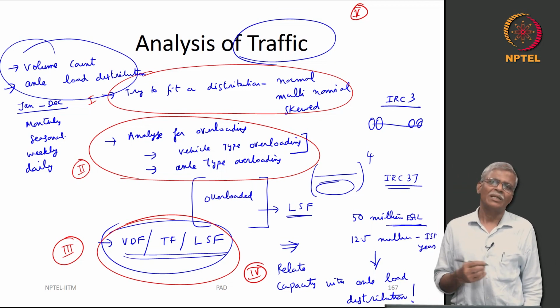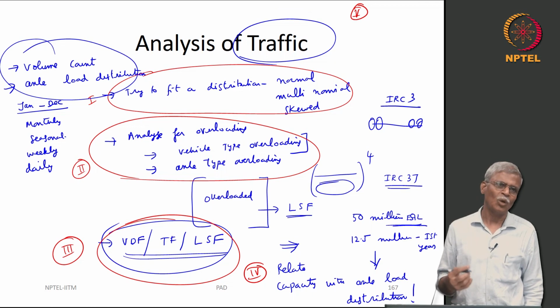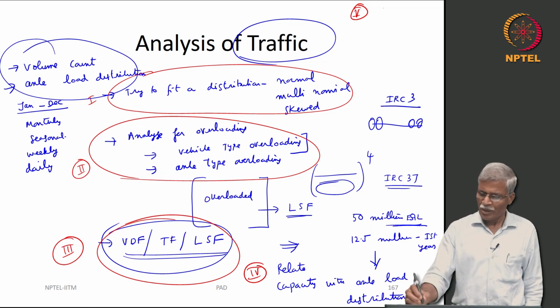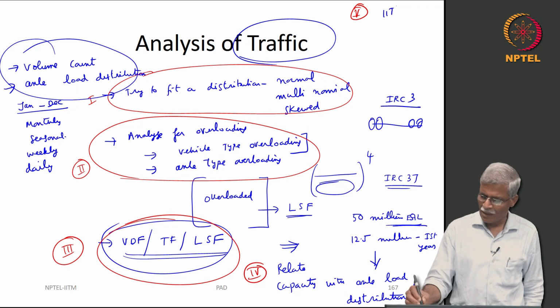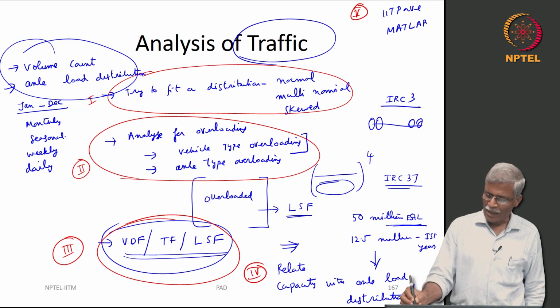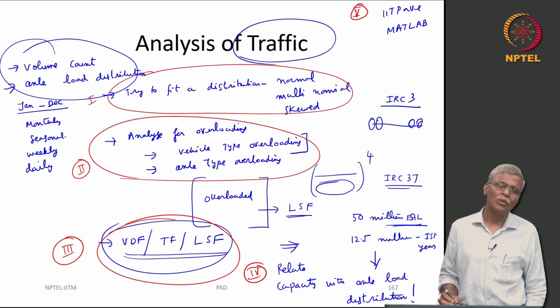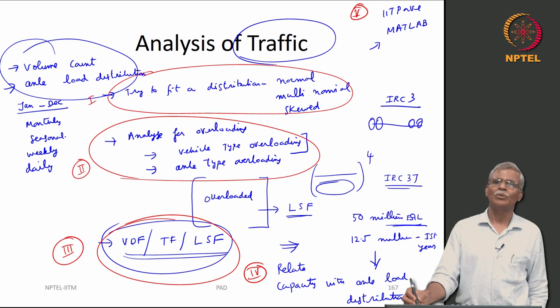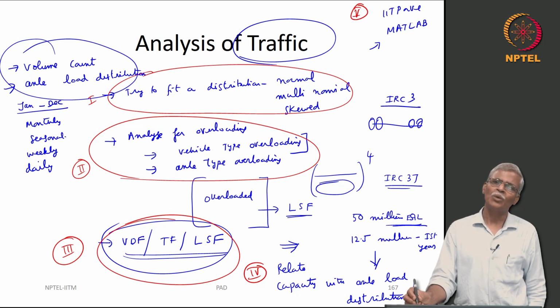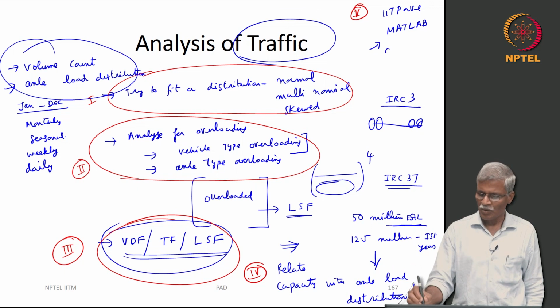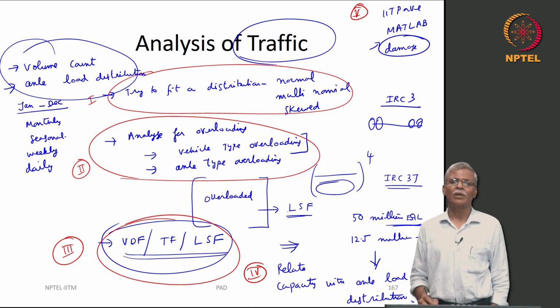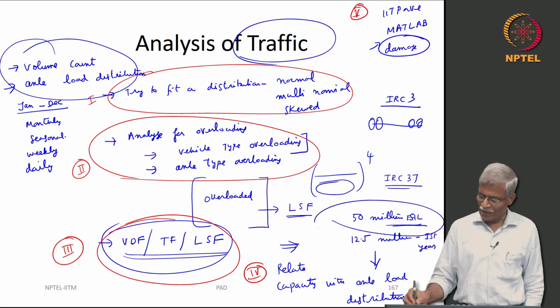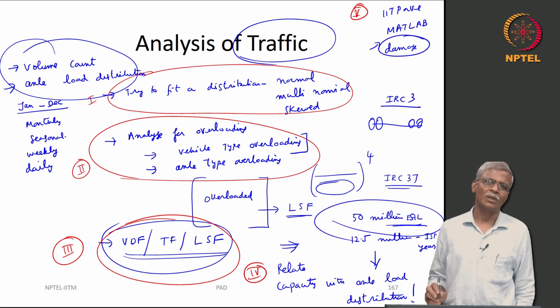If you are savvy enough in computers, and you know how to play around with the system, what you can do is integrate IIT PAVE inside MATLAB and see, for all the volume count and the axle load distribution that you are getting, whether you can use MATLAB to compute the damage for each and every load application, instead of just doing it like what you have done here, where you take one number and say that this is the damage.